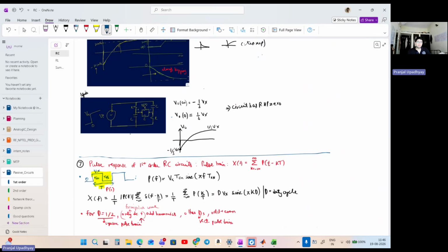Now we have an example of this circuit, and we are to find its response. Already I have sketched the answer, but let us try to arrive at this result by intuition. Okay, so now when I force a sudden change at the input, this capacitor will feel as if it is shorted, and this capacitor will feel as if it is shorted, and this capacitor will feel as if it is shorted. And thus, this impulse current can easily flow through this path, and no current will need to flow through the resistance. And that's why at initial time we won't find any impulse, right? That's the main reason, because all this impulse current can easily flow through this capacitor series network.